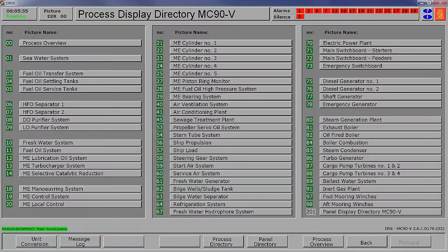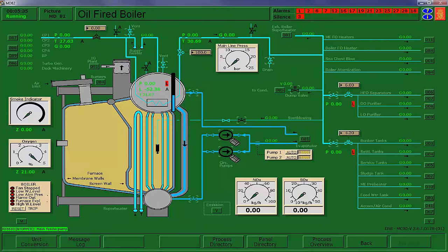We've got the proper valves open. Oh, by the way, too, on this steam drum, on the desuperheated steam drain, you would typically leave that open so that any water coming back, you would drain it out, and then once you've drained out your water, you're going to go ahead and close that.